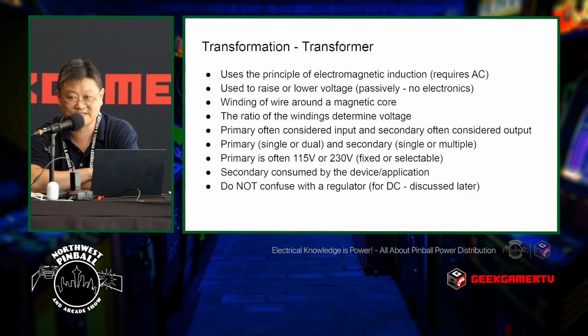The thing with these transformers in pinball machines is that they have multiple windings on the output side because there are different levels of voltage that are required. Solenoids run on high voltage, 50 volts. Flashes run on intermediate voltage, 20 volts. And power runs on lower voltage, 12 volts. And digital logic runs on an even lower voltage of 5 volts.